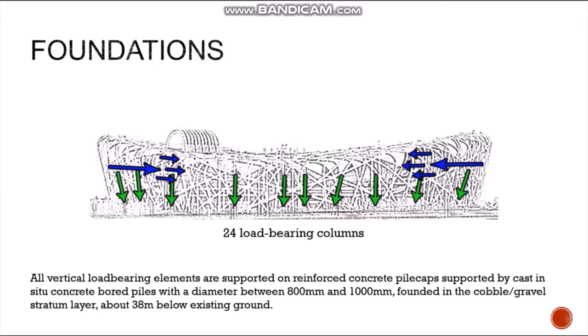First, look at the foundation. All vertical load-bearing elements are supported on reinforced concrete pile caps supported by cast in-situ concrete bored piles with a diameter between 800 mm and 1000 mm, founded in the cobble/gravel stratum layer, about 38 meters below existing ground.